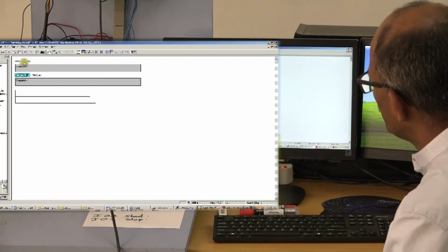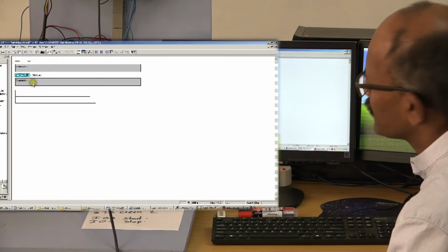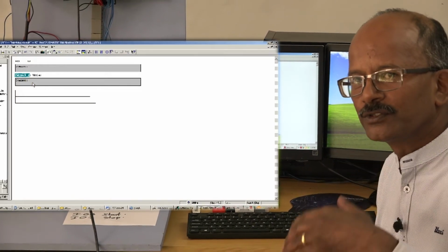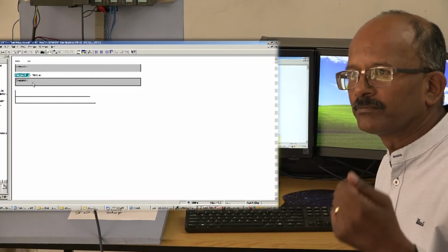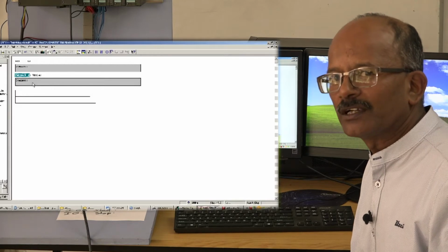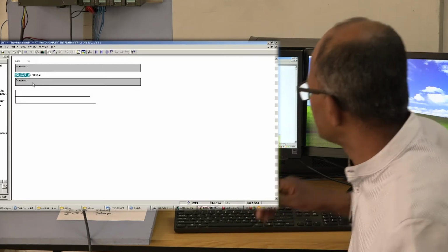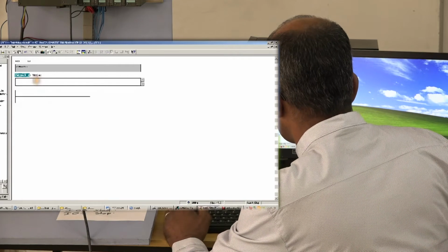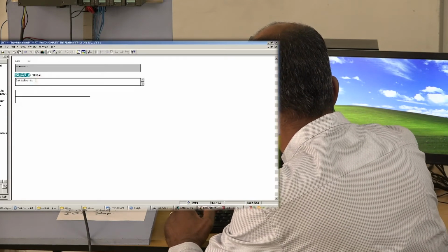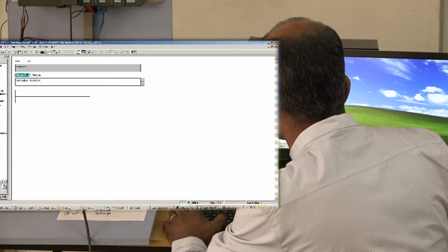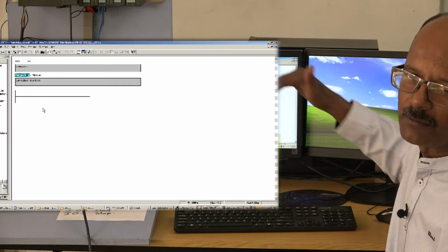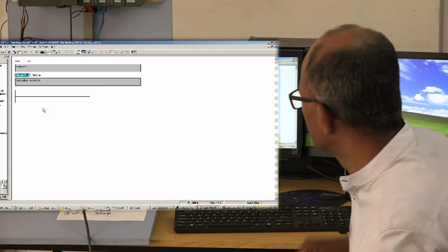Remember, you also have what we call comment lines. Comment lines are lines that would not be part of your program, but you could use it for putting terms of reference there or putting comments so that other people would understand what you are doing. So under comments here, I can, if I want to, write latching circuit. And that would now be for somebody else using this program. They will know what it's all about.